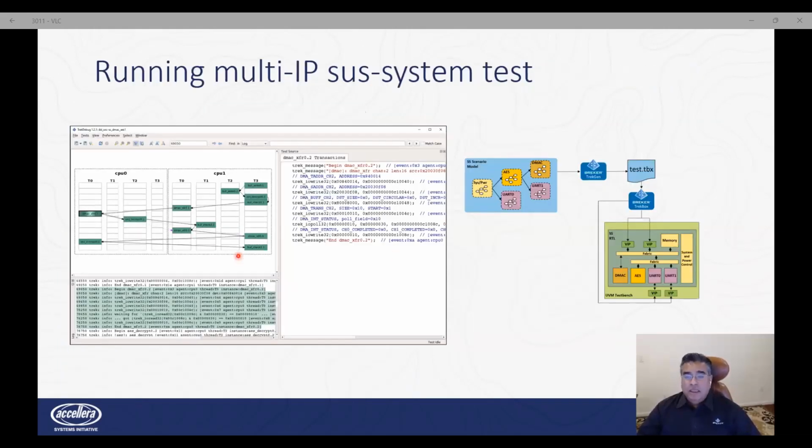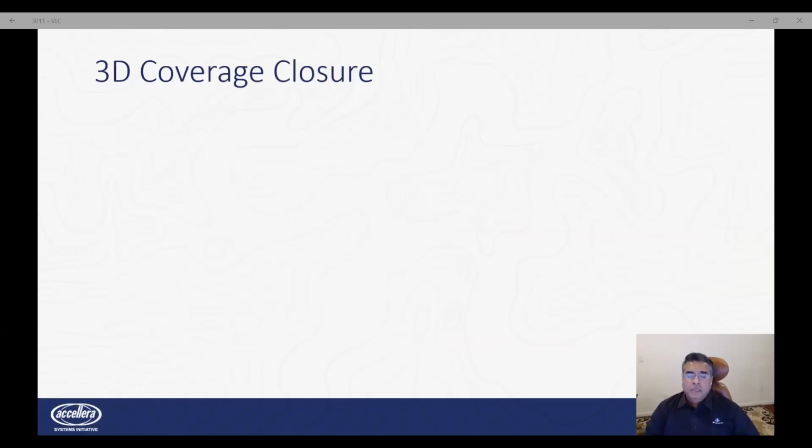We can run the test case, and now we get a schedule with different operations happening in each of our two CPU VIPs, our two AXI VIPs. We see over here a DMA transfer to set an input clear text, DMA transfer to set up the key, and then we do a decrypt, and then we do a check, and so on. We can click on the DMA operations. We can see the register writes he will send into the interface VIPs for AXI, and we see the test executing. Using UVM++ with our UVM environments gives us a number of advantages that come from the PSS tools.